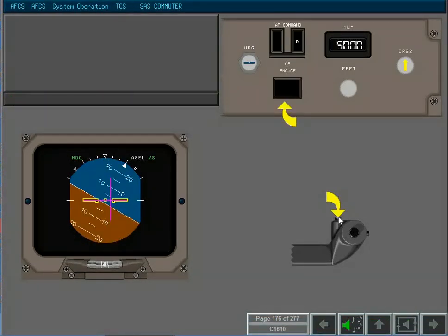Operation of TCS with the autopilot engaged overrides the autopilot commands to the servos whilst the button is pressed. The AP light on the flight mode panel extinguishes to indicate the declutched state. The flight director pitch command bars are zeroed to the aircraft symbol. Steering movement at the control wheel is directly realized at the flight control surfaces.